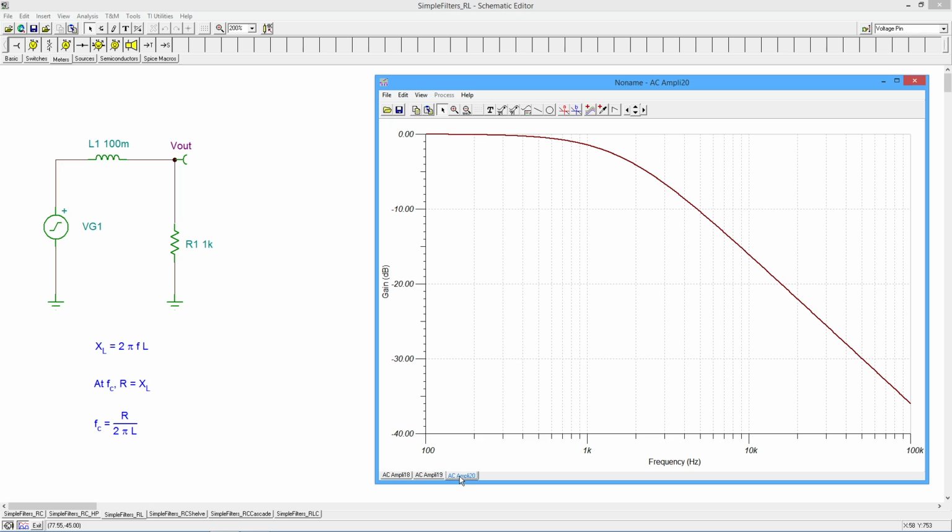Generally speaking, we'd actually prefer to do circuits using caps rather than inductors because caps behave more ideally than inductors do. Inductors have issues with internal resistance, coil resistance. We have issues with stray magnetic fields and things like this. So caps are a little bit better behaved, and if we can, we'd rather use caps than inductors. Now with simple kinds of circuits like this, you can do it without inductors.